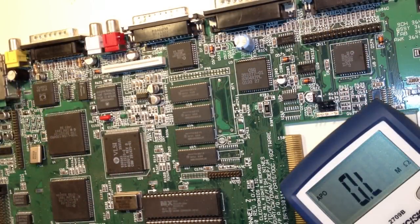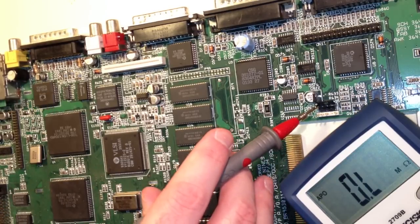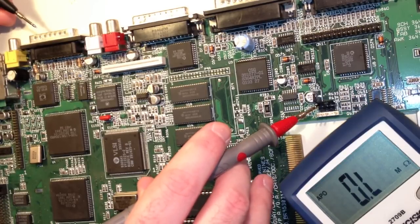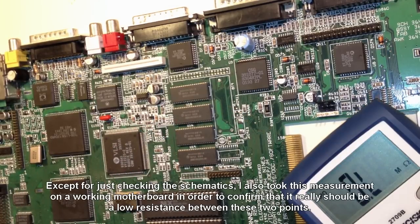Okay, now VCC, or the 5 volts rail, can easily be found at the left pin of the power connector for the floppy disk drive. So I'm gonna put one of my probes there, and I'm gonna take my other probe and put it at pin 23 of the video connector. So let's see what we get here. 9.82 kilo ohms, so almost 10 kilo ohms. That's insane. We should get basically 0 ohms there, not 10 kilo ohms.